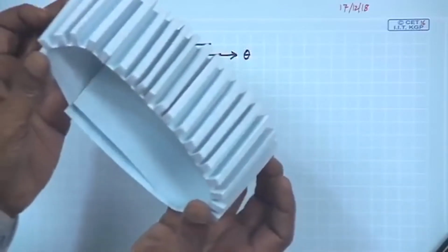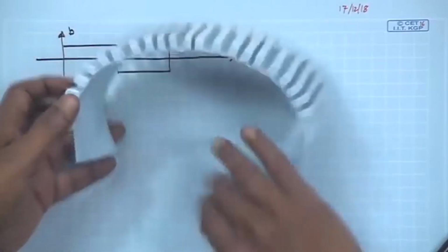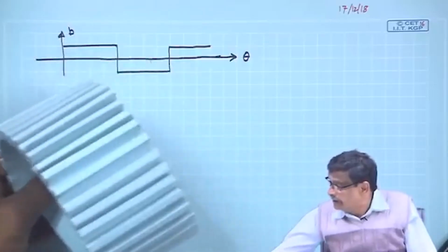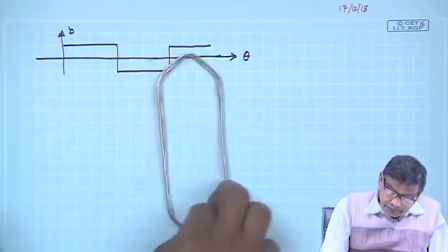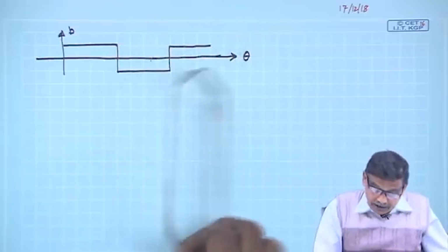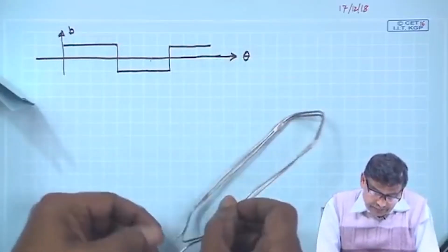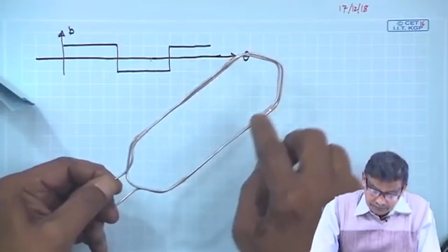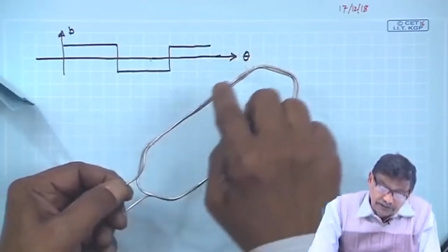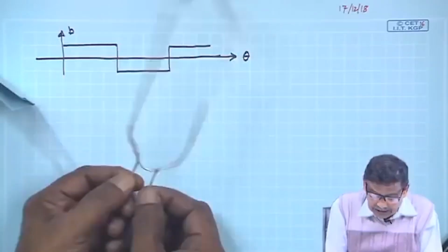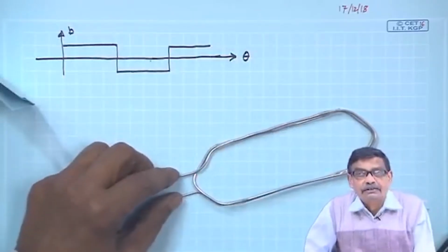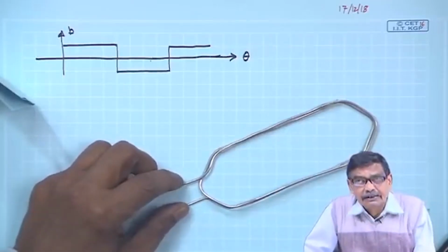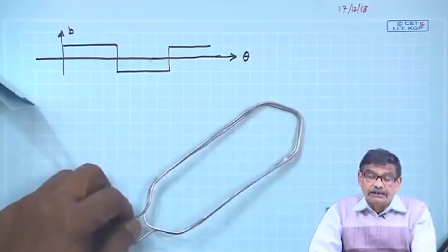Now, in this rotating machine, what happens is this: how to place the conductor and what is a turn. Suppose this is the rotor, it has a diameter. You take a coil, it is a multi-turn coil. In fact, it is a two-turn coil. How have I manufactured it? I have taken a conductor, it goes like this once, comes back, then once again goes to the same slot, comes back, and ultimately you have these two free terminals, which I was calling x1, y1, or 1 dashed, things like that.